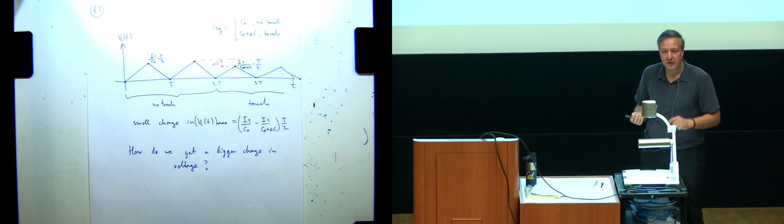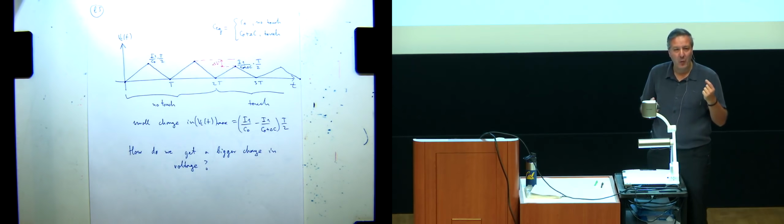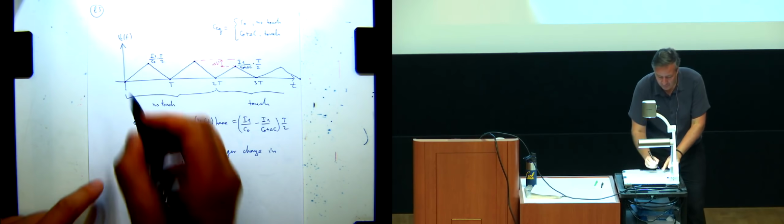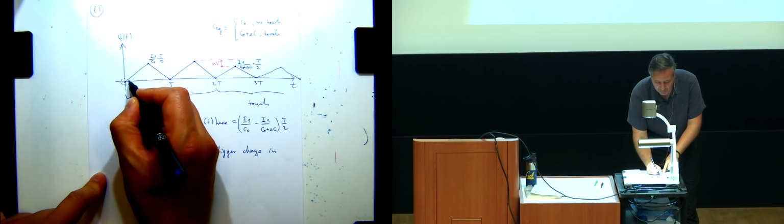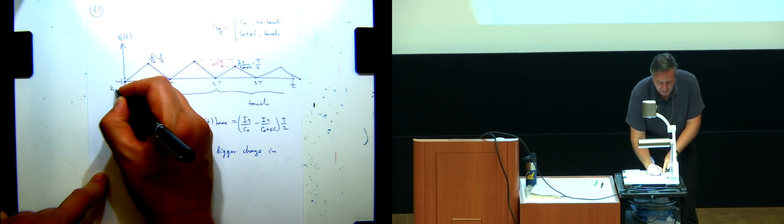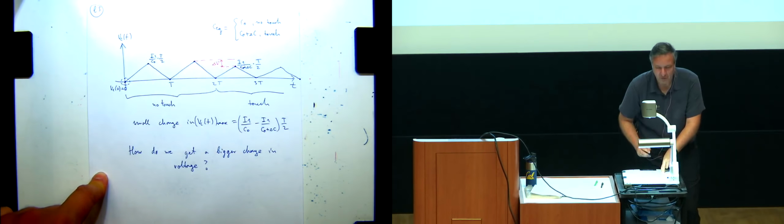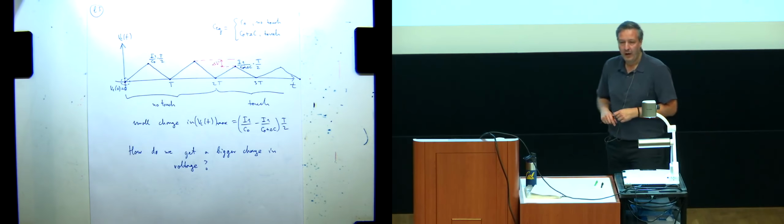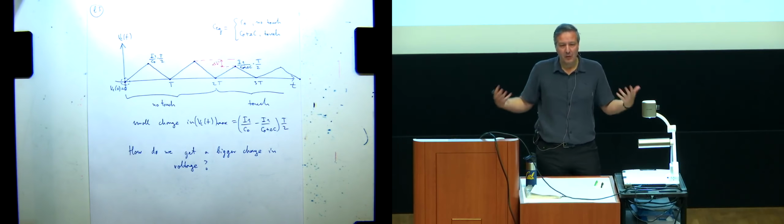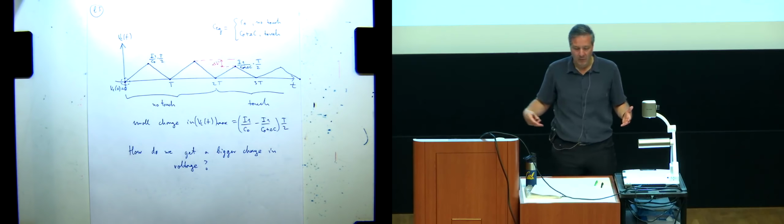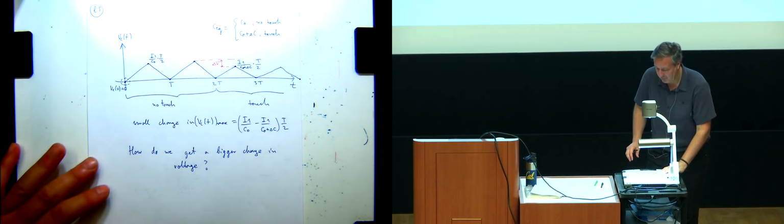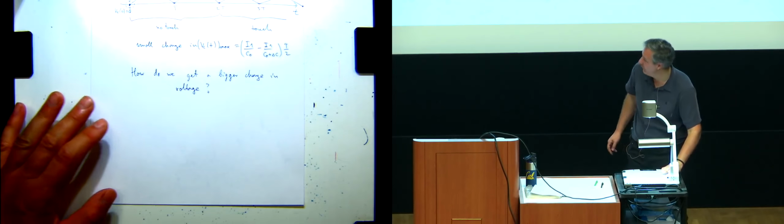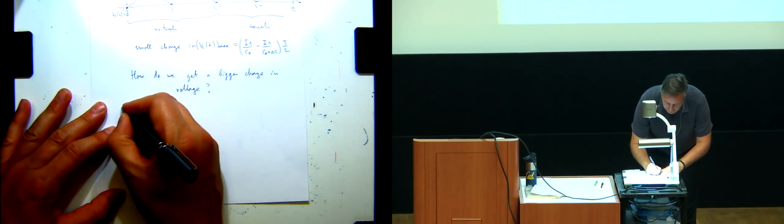Before we do that, I just want to go back and clarify one little point, and that was that I sort of assumed here that VC of 0 was equal to 0, right? I need to somehow guarantee that at the beginning of the measurement, right? And so the way to do that is I'm going to introduce another element that exists in circuits, and that's a switch.